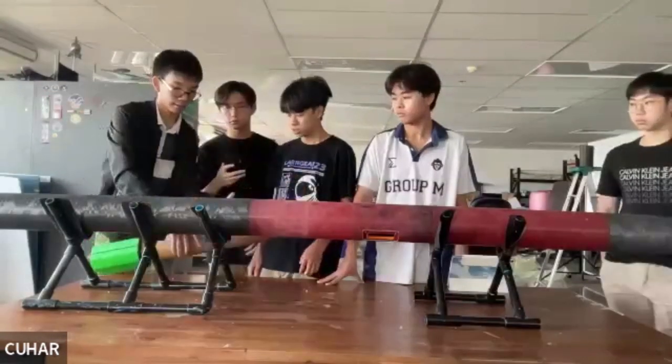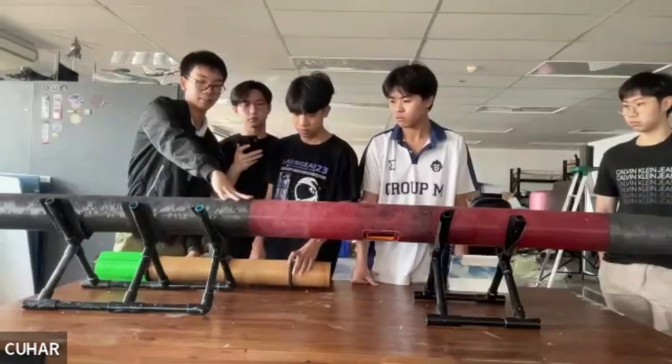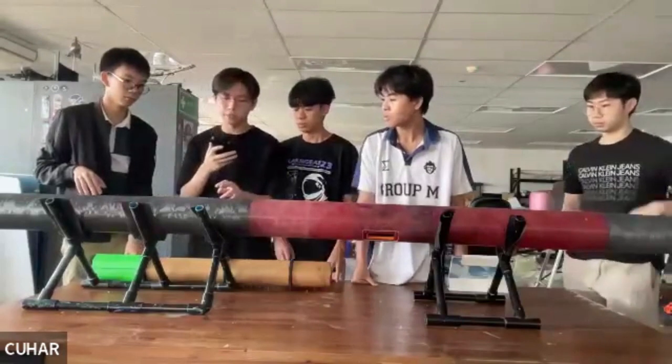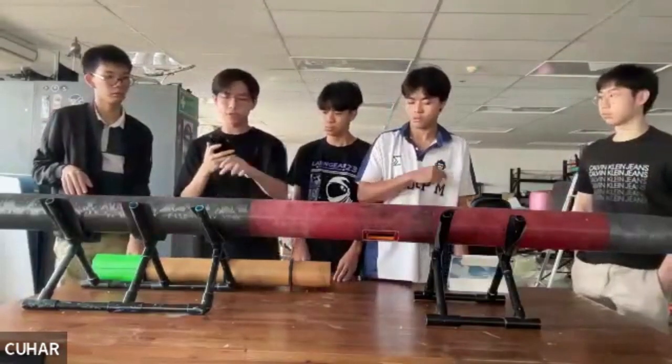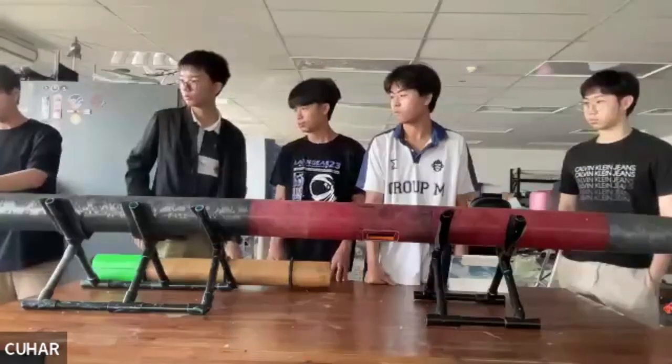And then the connection between the booster section and the drogue parachute section, basically we have a... Okay, before we move on, can you show me where your rail buttons are going to be and how you're attaching them to your rocket? Okay, so there will be two main rail buttons, COTS rail buttons. The first one will be around here, which is at the CG of the rocket, and the second one will be at the aft end around here.